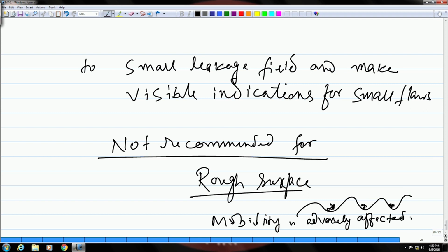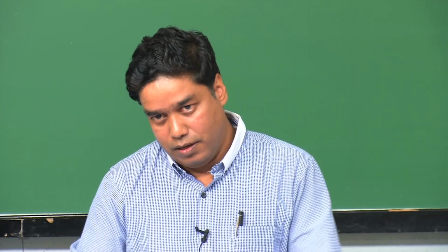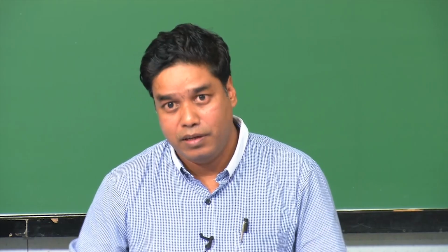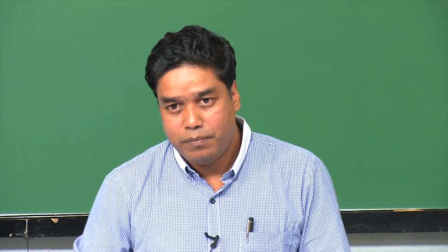Okay. So, for a rough surface, dry particles are always recommended. Because in that case you do not have this problem of particles settling down at the valleys. So, if you have a rough surface, like for example the surface of a casting, many parts are made by casting.